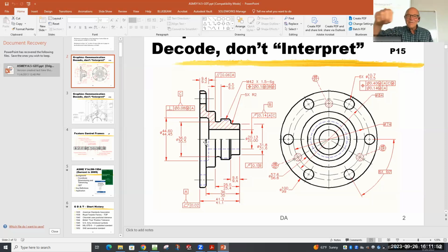And you just take that and you touch it all over, you drag it all around. Then electronically in a computer, it tells you whether or not it's flat enough. But visually, the mechanics of this makes more sense to me. You drop it down, you drag it all around, and make sure that it drags around on something that is itself flat. And granite is used because it's so stable.